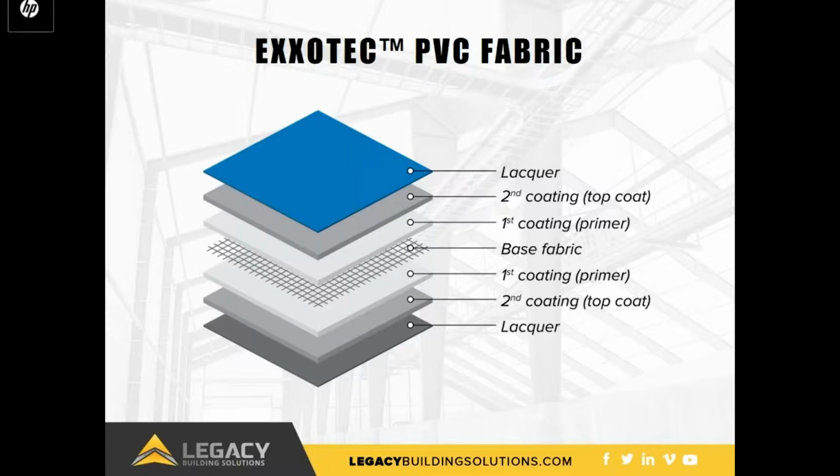Another common question is how the strength of the fabric compares to the strength of other metal buildings such as steel. Coated PVC fabric like Legacy's exclusive EXXOTEC provides 7 layers. The strength of the material comes from the base layer called the scrim. Both sides of the scrim are protected by a primer, a protective coating, and a top coat lacquer. The primer layer is designed to inhibit bacteria, mold, and UV rays, as well as enhance the chemical bond of the coating. The top coat prevents UV rays from penetrating the inner layers while providing a waterproof barrier and protection to the scrim.